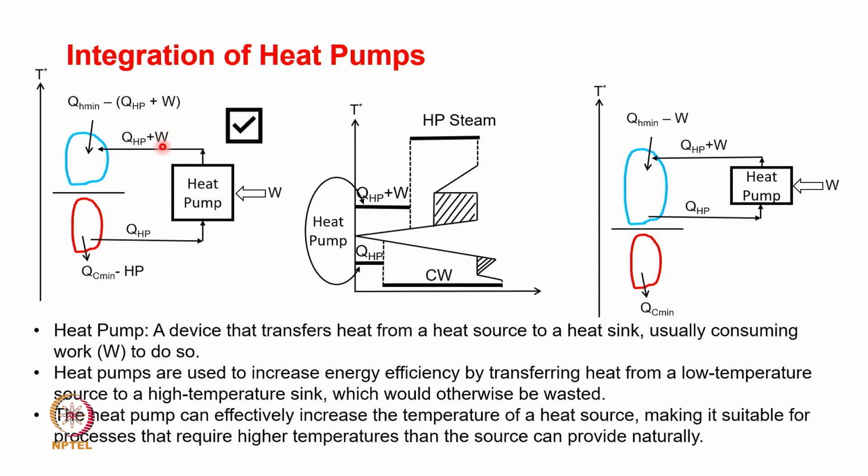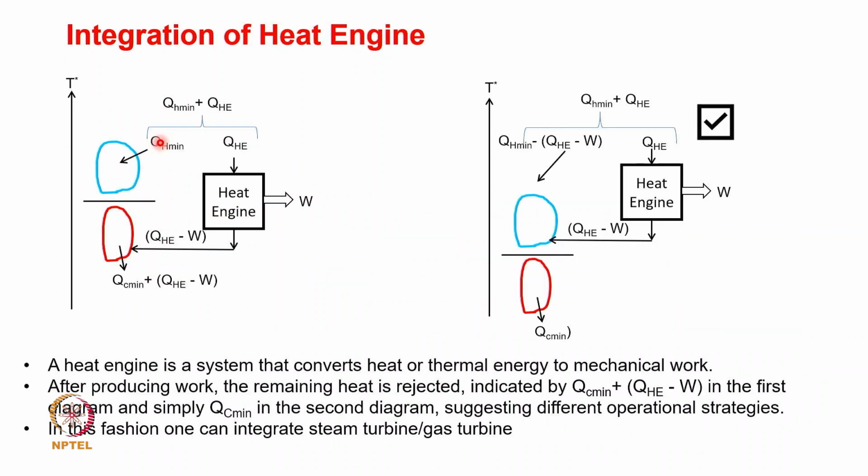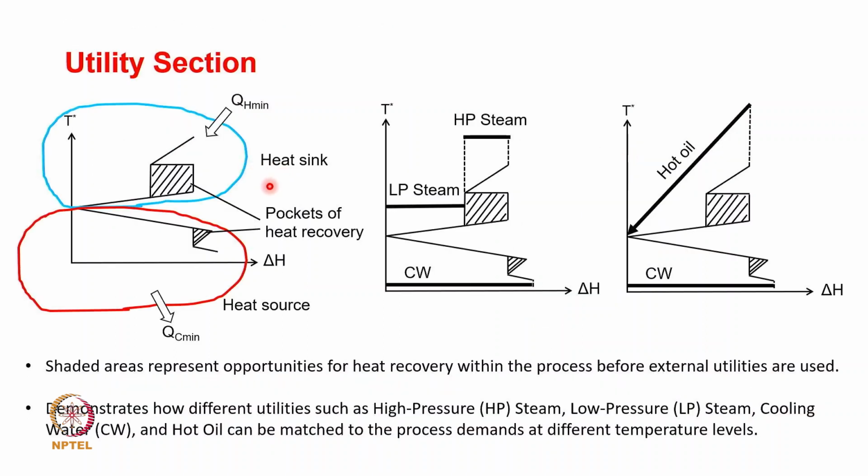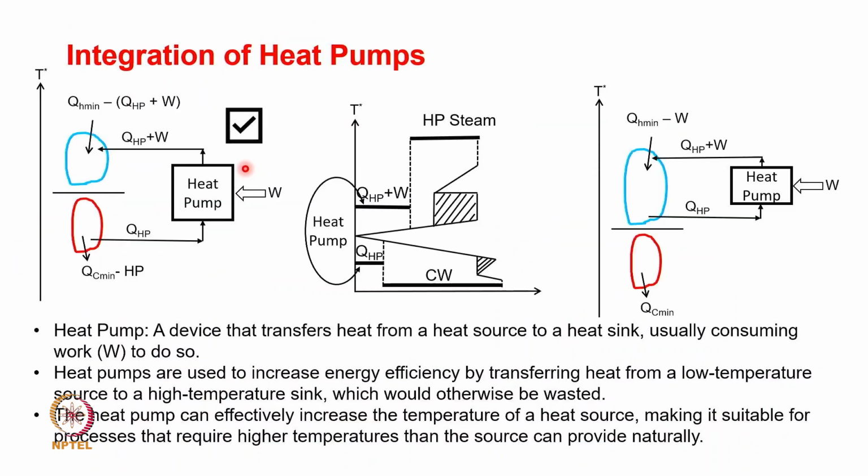So the key thing to be looked into here is that when we integrate a heat engine, we never do it across the pinch. We will only do it above the pinch. While when we do a heat pump integration, we always do it across the pinch.